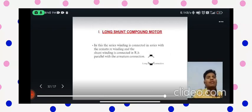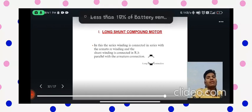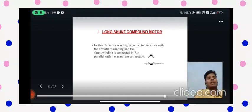In the DC compound motor, we are going to see about the long shunt compound motor. In this, the series winding is connected in series with the armature winding, and the shunt winding is connected in parallel with the armature connection.